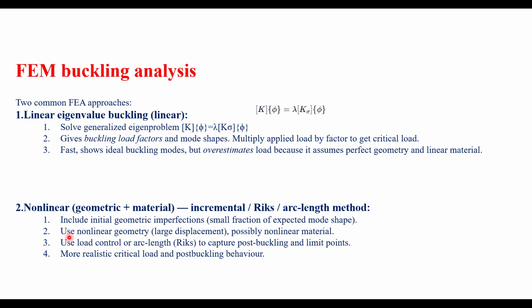So it will consider the large displacements into account and give the results accordingly. Next, it will also consider the non-linear material. If you do the analysis in OptiStruct non-linear, I can even show how exactly we consider the geometry and the material non-linearity into account.